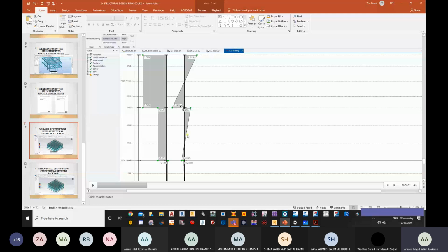Okay, now most of the cases in reality are not going to be axially loaded. You have studied in Design of Structures 1 that we have axially loaded columns, we have columns loaded with uniaxial bending, with one bending, and then we have columns loaded with two-direction bending, and we're going to see it. Most of the cases when it comes to reality are going to be loaded with uniaxial or biaxial bending, because normally we don't have a symmetric arrangement of beams, unless, for example, we are talking about parkings or similar areas of shops, which is very rare.